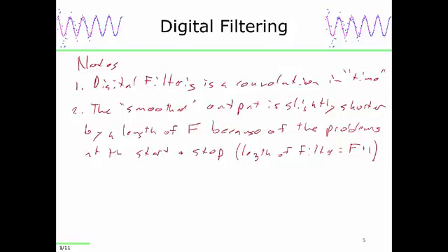But we lose 1/2 of f on one side, a little less than 1/2, and a little less than 1/2 on the other side as well. That's a fact of life. It's part of the cost of doing business with digital filtering. The solution is to just acquire a longer data set, either before or after. Make sure you have plenty of data before something interesting happens, and continue to acquire data long after something happens, and you have plenty of opportunity for throwing those data points away throughout the digital signal processing.